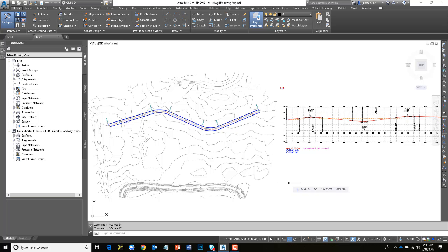In this session, we're going to look at how we can create transitions using the out-of-the-box Civil 3D subassembly components. So using this technique, we can transition thicknesses, widths, slopes, virtually any object. And we're going to do it just by creating a number generator that's going to calculate the transitions for us. I'll show you what I mean.